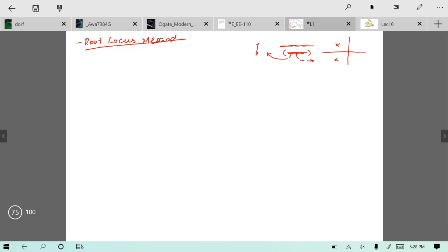So you can change this characteristic equation by changing zeta, or you can change zeta by changing system parameters, just like in your mass spring system, which depended upon k, b and m. By changing the spring constant, the frictional constant and the value of the mass, you can change zeta, eventually change the characteristic equation, and eventually change the location of the poles. This you are doing intentionally. You are moving your poles to some location by changing k, b and m.